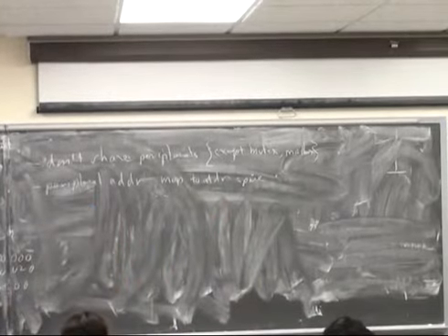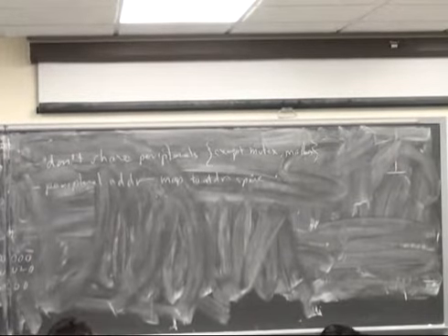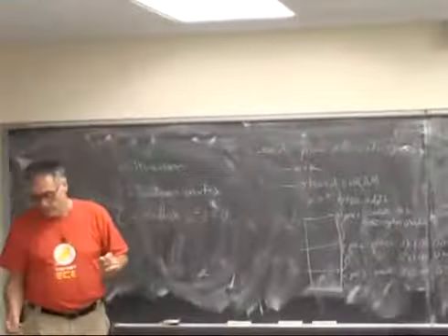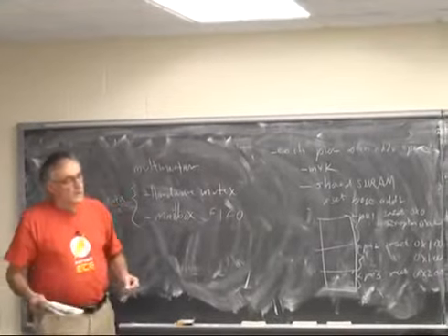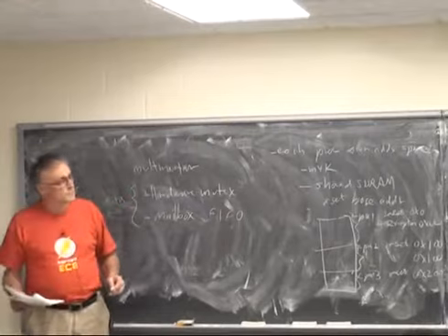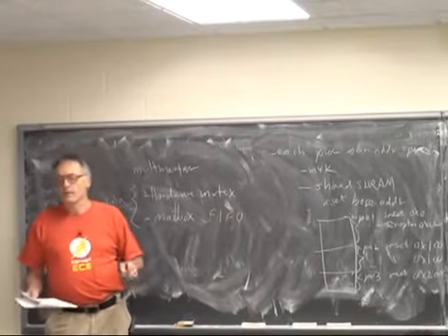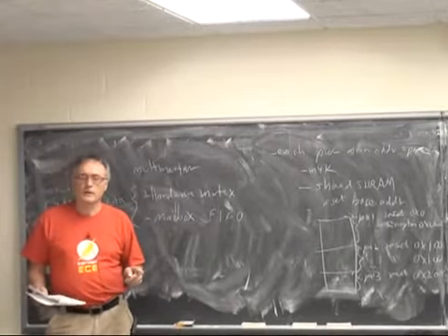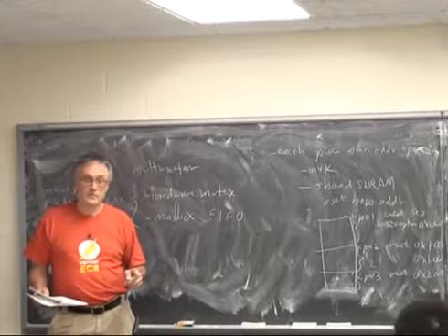So SOPC Builder generates a single module that has all of the CPUs defined in it, and you can include that in your Verilog file. I'm trying to figure out if the Altera monitor can handle the concept of multiple CPUs.